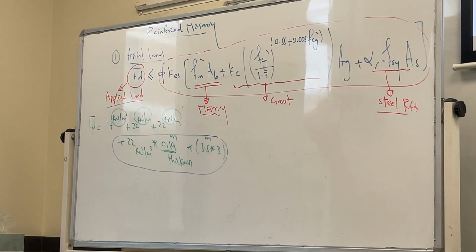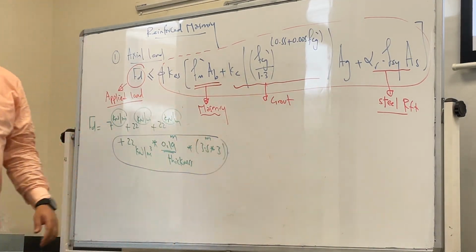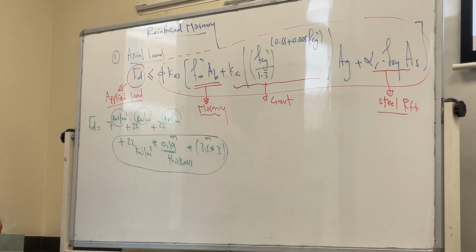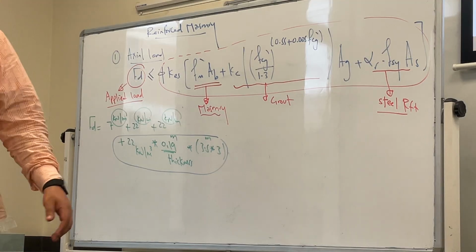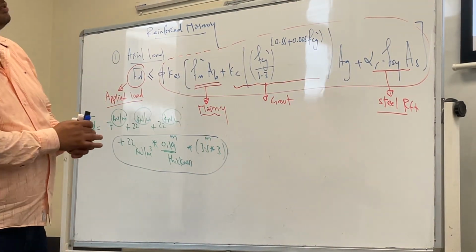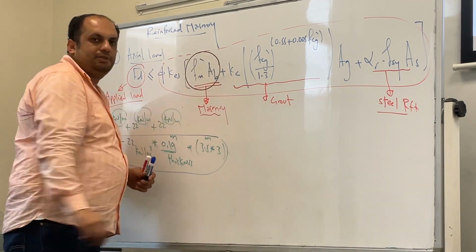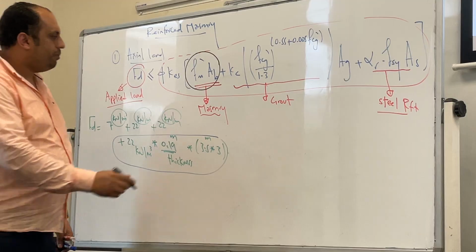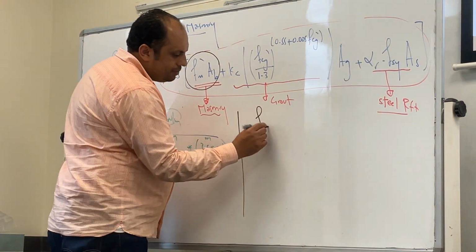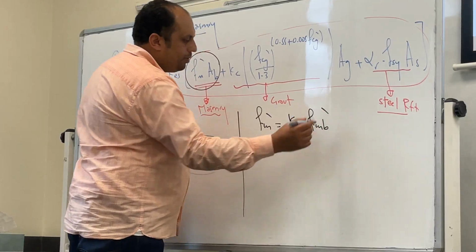Now the second part is the formula of the capacity. If you try this, what is the problem? It doesn't give you anything, right? So you need to assume. What you know is only the masonry type and the grout. So he gave you some information about that. How can we get f'm? We have done this many times. K, H, f'mb.